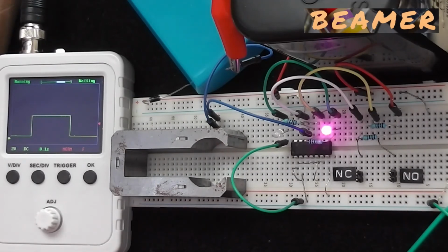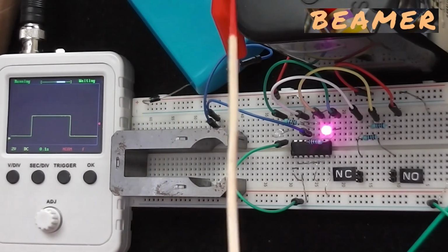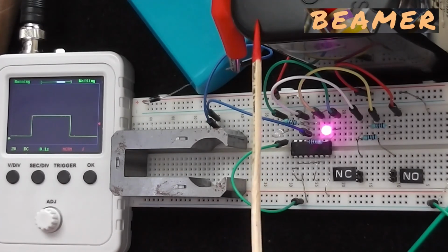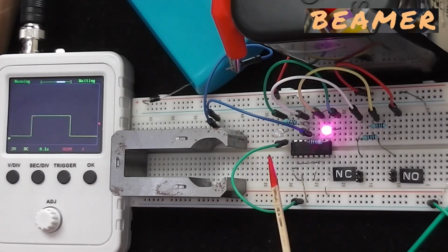So here we are back on the bench, and we have in front of us the infamous DSO, its battery power pack, a 6-volt lantern cell, a red LED and a green LED, and in the middle there the chip is the CD4011. As I said, I didn't have the 4001, which I could have used, but I preferred this simply because a double NAND gate gives you the option of having the wiper, as we've discussed, at 0 volts.